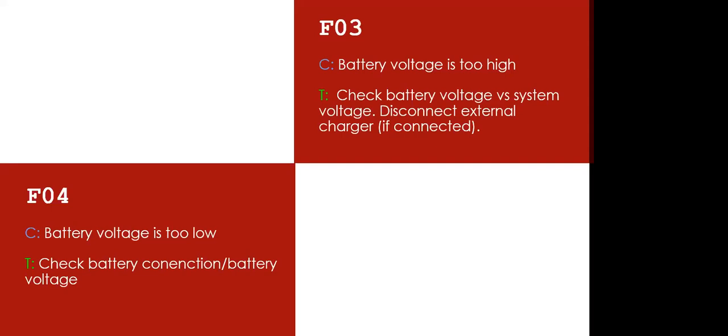If you set program 28 to be 44 and your battery voltage is about 43, the inverter will not recognize it as an appropriate voltage to operate on until you get to the 44 that you set. This helps you manage your battery so that you don't overuse it and the battery is not just going flat before the inverter goes off.